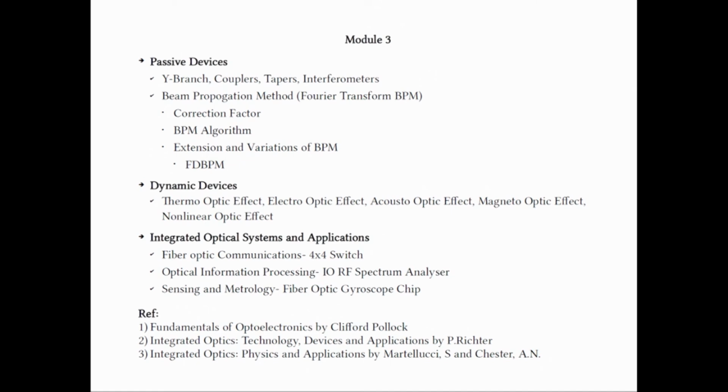So, it is also possible to create devices for many applications like metrology. For example, if you have an array of fiber Bragg gratings and the signal coming from different sensors is to be analyzed, it is possible to analyze it by using these integrated optical techniques, by creating gratings and other components on the same chip.